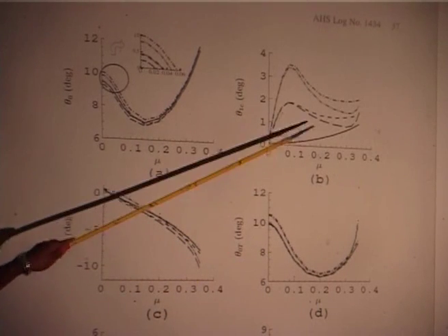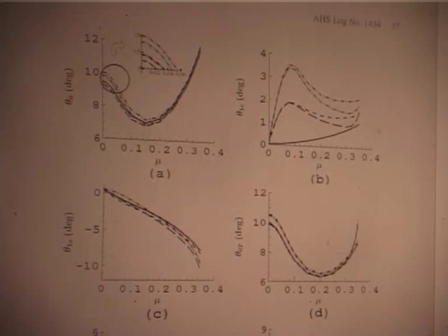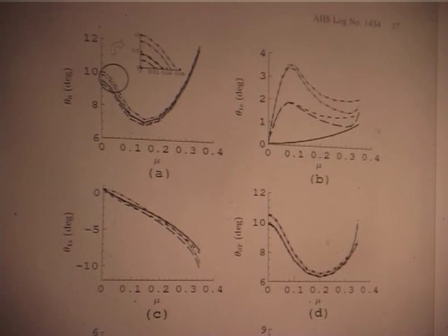This was a point of debate. Why the helicopter? It is like this: the pilot wants to fly forward. Usually the general tendency is what? If you want to go high speed, you give more angle. But here initially you give more angle, then as you increase the speed you start decreasing the angle. So, from hover you go to very large and then you start coming down. It defies the traditional convention.